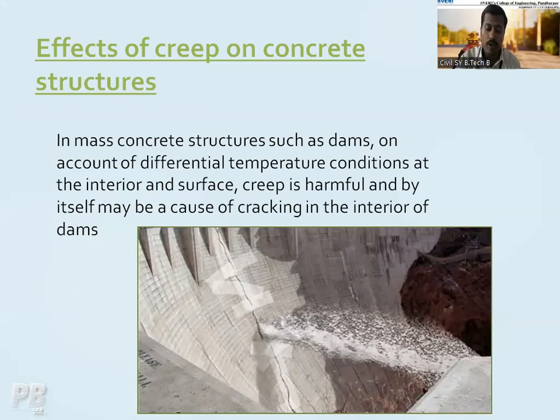Actually, there should not be any deformation at first. If you observe some cracks or deformation starting in the concrete body, cure it immediately, because for such mass structures like a dam, or bridges, if some cracks are there on the pier structure, they are not good for that structure. It will definitely reduce the life.